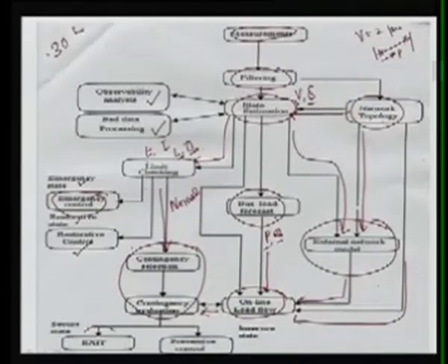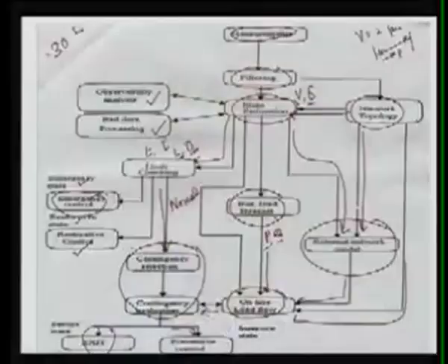So if it is a secure state, then you can go for optimal power flow, and so on. If your system is in an insecure state, then you have to go for some preventive action, and at the same time you can apply security constraints, optimal power dispatch, because here you are going to control something. You are going to change the settings of some of the outputs of the generators, maybe the elements of your power system. At the same time, it is possible that we can set our generators in such a fashion that we can achieve the minimum cost operation, and then it is called security constraint optimal power dispatch.